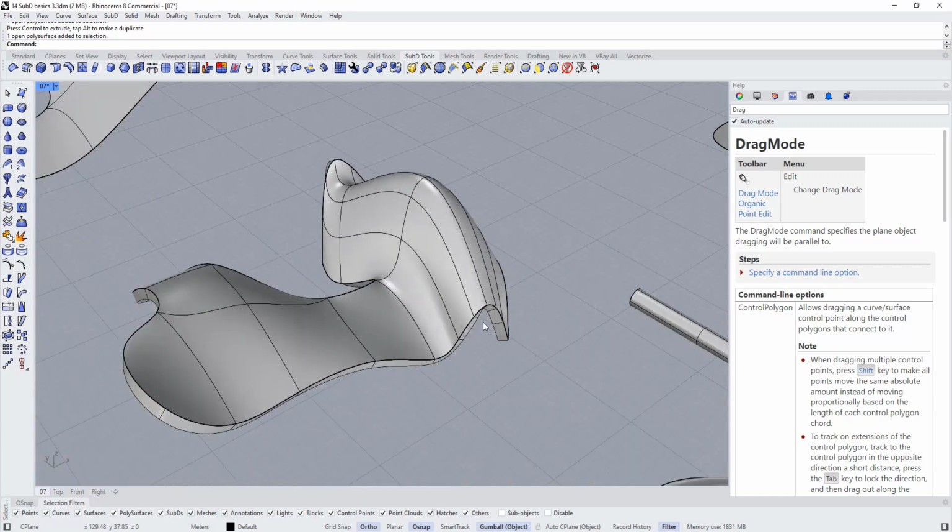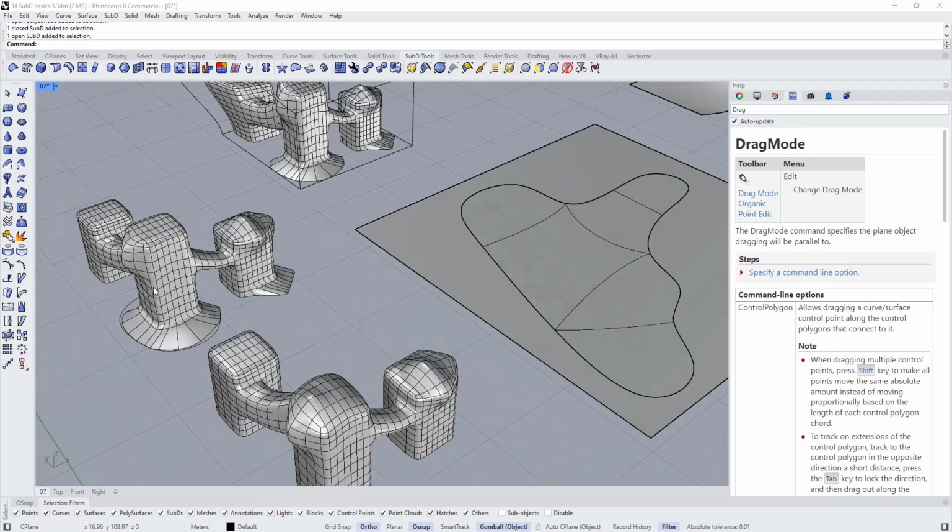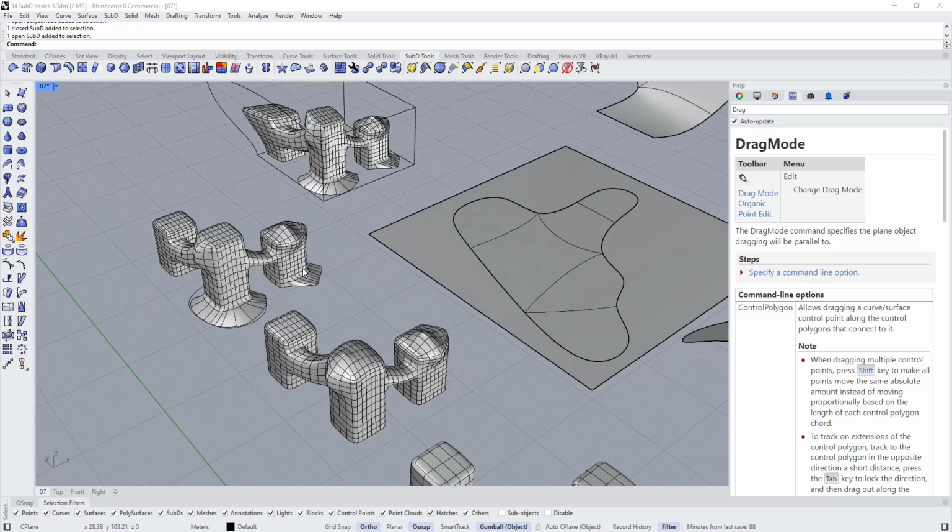And also the offset command, don't use it before having a backup, or set delete input to no also. And same thing to subdivide because it is irreversible.